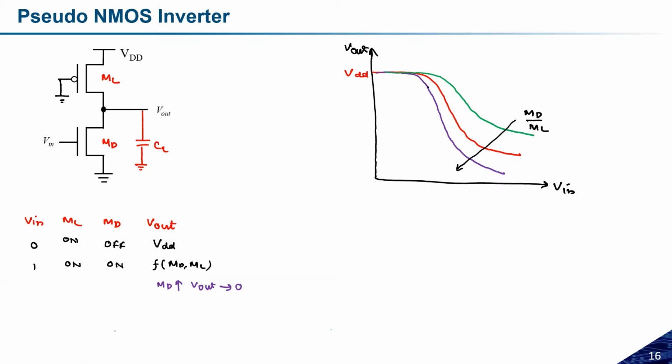The important point over here is that VIL will shift, just like in the previous case. Okay, so VIL will shift, VIH will shift, VOL will also shift, and VOH can also shift. Based on that, you can calculate what the noise margin is.